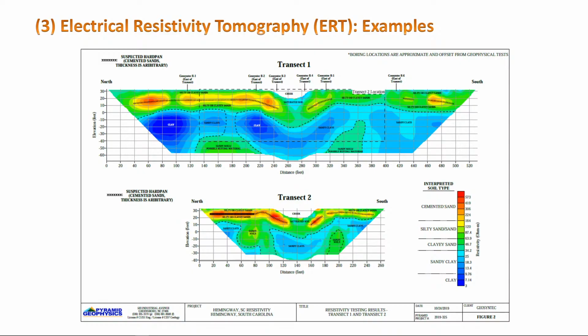And then you see here in this transect, you make your measurements, and after you make your measurements, there is software that does inversion to convert resistance to resistivity. So that's done by software. It will convert based on your distances and all these things. It will convert this to your resistivity value. And now here this is your resistivity value.